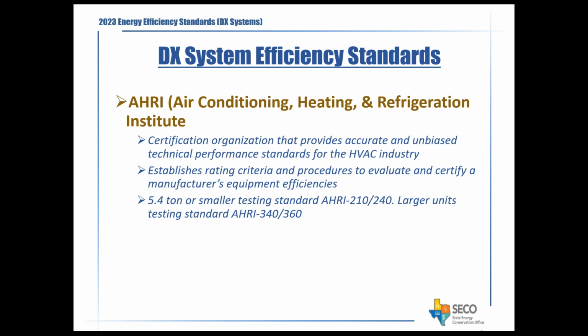Larger units, which are bigger than 5.4 ton, go through a testing standard that's AHRI 340/360. Chillers have their separate status, but we're not covering chillers because there have not been any significant changes in their testing procedures. Mostly it is the DX system that's been impacted.